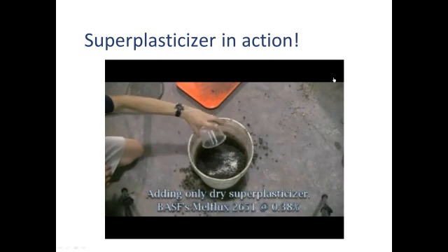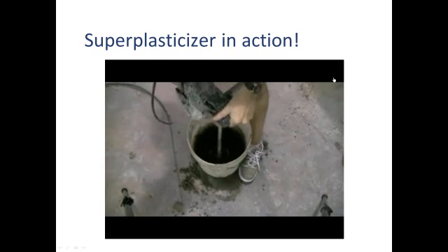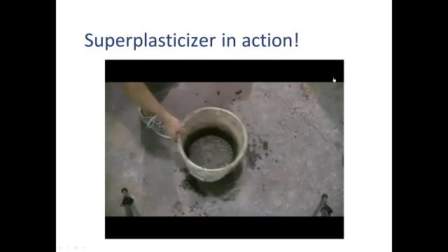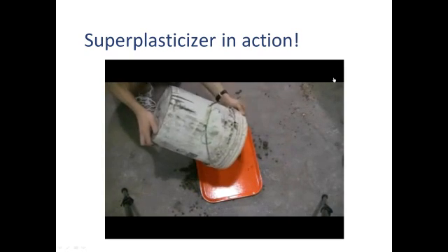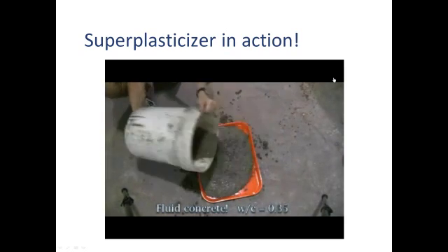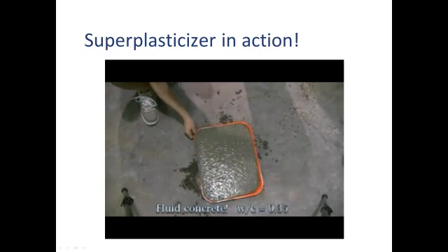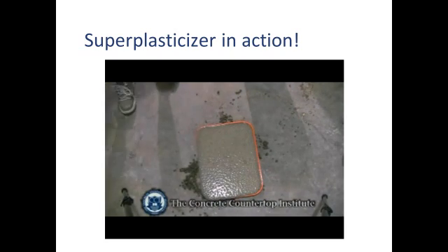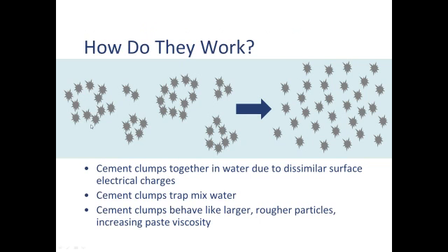Here I'm adding a dry superplasticizer at a moderately low dose, and this plasticizer is developed for bagged products. Now look at the consistency when I pour. I haven't added a drop of liquid to it, but now it flows like pancake batter. Its water cement ratio is still 0.35. With a little bit of shaking, it self-levels, bubbles are coming out, and that is what I call adding powdered water. I'm adding workability.